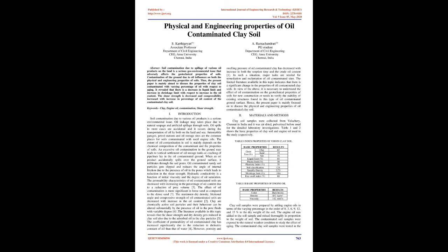Clays are chemically active soil particles and their behavior can be altered substantially by the presence of oil in the pore fluids to a variable degree 6. The literature available on this topic reveals that the shear strength and dry density are reduced in clay soil also due to the oil adsorbed on the clay particles 5. The coefficient of permeability of oil-contaminated clay has increased significantly due to the reduction in dielectric constant of oil compared to that of water 4. However, porosity and swelling pressure of oil-contaminated clay have decreased with increase in both the sorption time and the crude oil content 1.